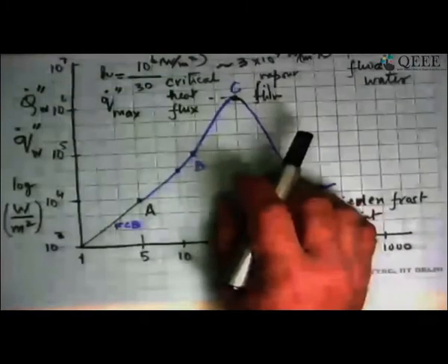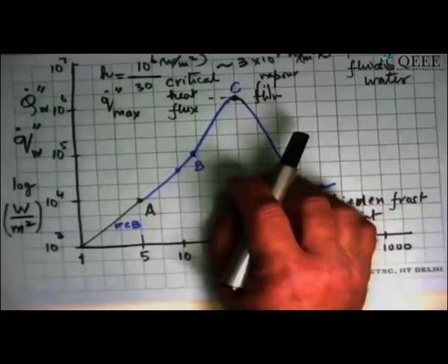30,000 watts per meter square per Kelvin, and water in forced convection you will be getting 1,000, 5,000, 8,000, maybe 10,000 watts per meter square Kelvin. What you are getting here is something 10 times bigger than what was happening, and that's the reason why, whether it is chip cooling or many of the other applications, you want to exploit boiling as a technique for heat transfer. With vapors, that number comes down to hundreds in forced convection. So 100 for vapors, thousands for liquid, and tens of thousands for boiling heat transfer. That's the order of magnitude you are seeing happening in the case of, say, water.